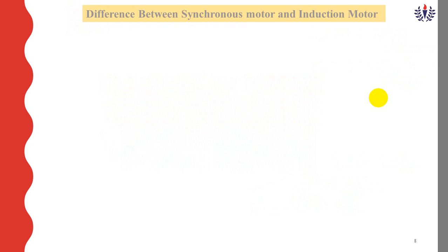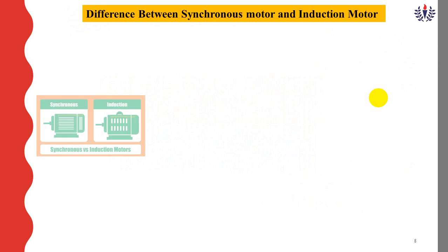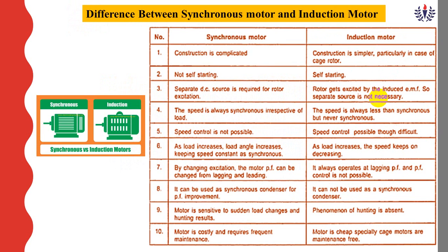The last topic: difference between synchronous motor and induction motor. Please take down, there are 10 points. In a synchronous motor, the construction is complicated, but in an induction motor, the construction is simple. A synchronous motor is not self-starting, but an induction motor is self-starting.